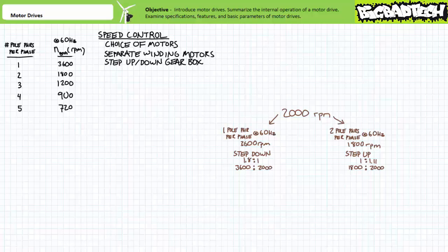It should be noted that most fixed-speed machines making use of gearboxes actually step motor speed down more than these simple examples suggest. Additionally, it should be noted that the gearbox exchanges speed for torque. As speed goes down, torque goes up, and vice versa. Regardless, given the right ratios, through mechanical modification of pre-existing speed levels, we've now effectively thrown wide open the doors to a theoretically infinite range of speeds.